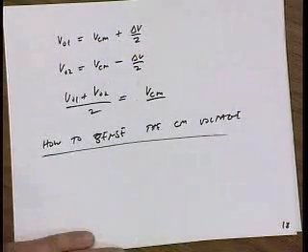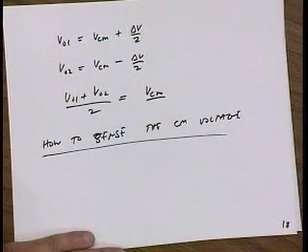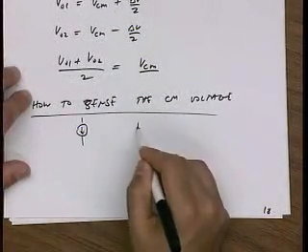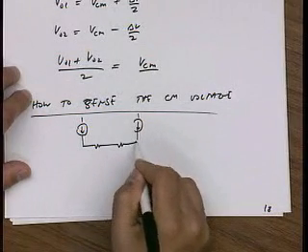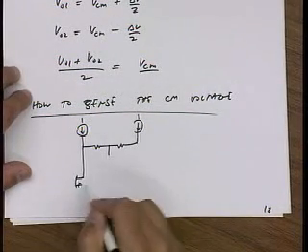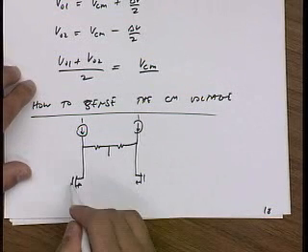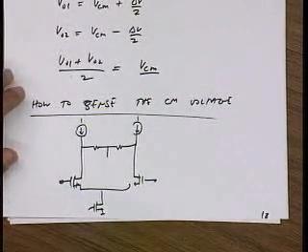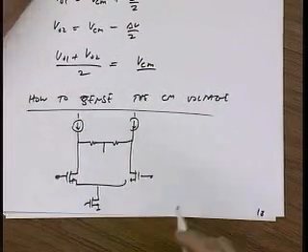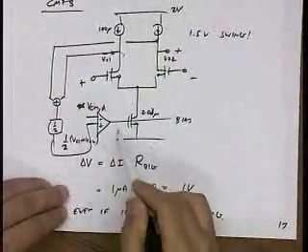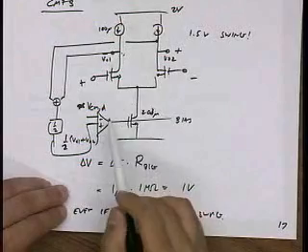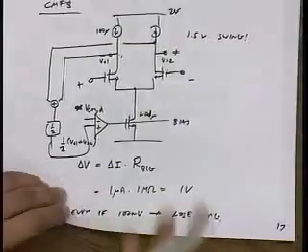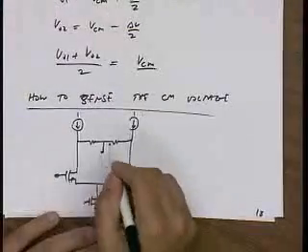Okay, Vincent? Can you just use 2 resistors and then tap in the middle? Yeah, so this is probably one of the earliest techniques that people have used. You just use 2 equal value resistors. And in fact, if you look at this, maybe I don't even need this amplifier, right? Maybe I can just take this voltage, tie it directly to this point, because this is inverting. Come back to that.